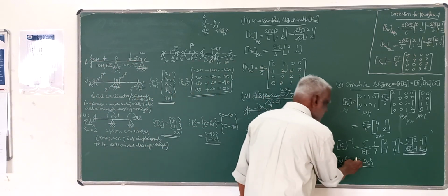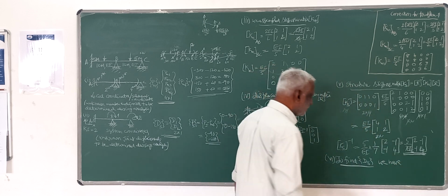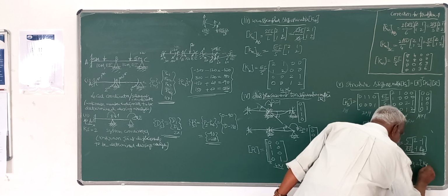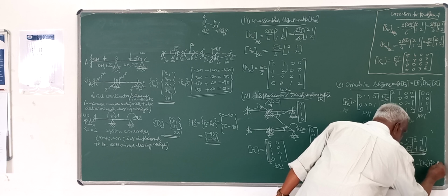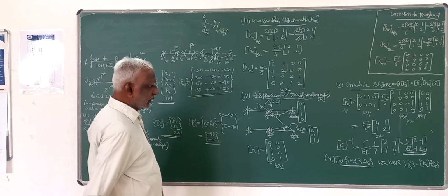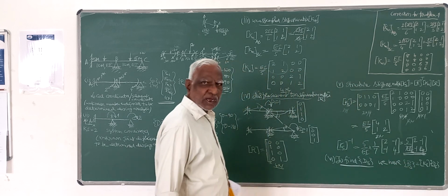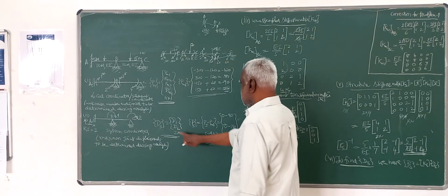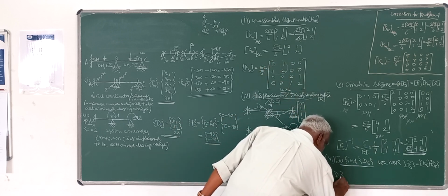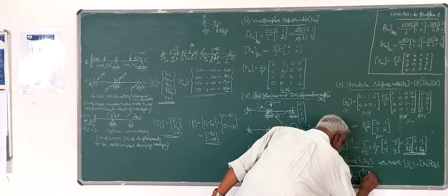So for finding this ds, we can use the force displacement relationship in system coordinates, that is Ps is equal to Ks into ds. This also I already told, that is the force displacement relationship in global coordinates. Here we have generated Ks, Ps also we have generated, so that ds we can determine. Therefore, ds is equal to Ks inverse Ps.